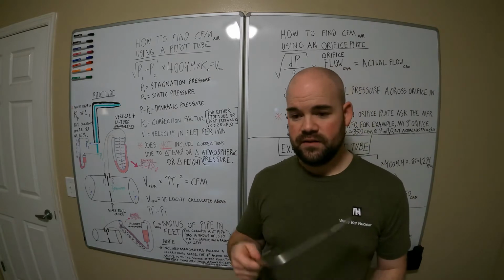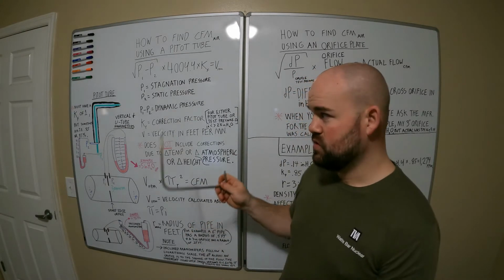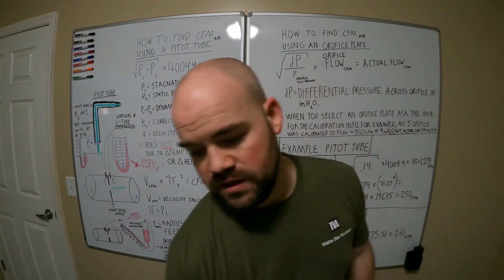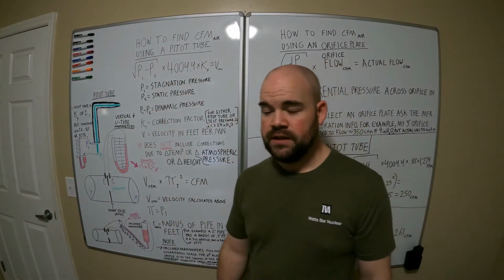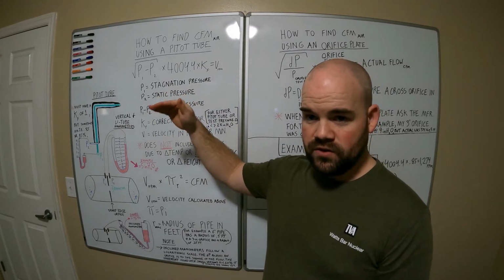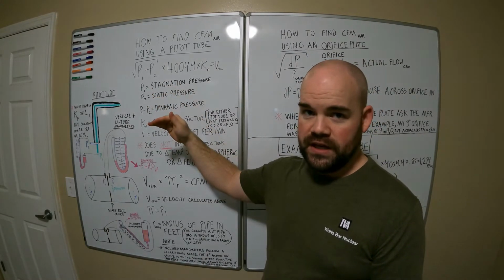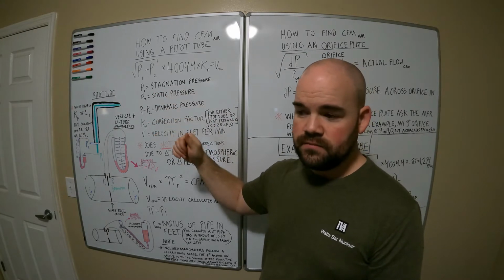Superflow has a board that you can look at, or it's simple math. You just take the square root of the test pressure that you want to be at by the test pressure you're at. It'll give you a multiplication. If it's greater, so if you're testing at 32 inches of water and you want flow at 28 inches of water, then it'll be less than 1.